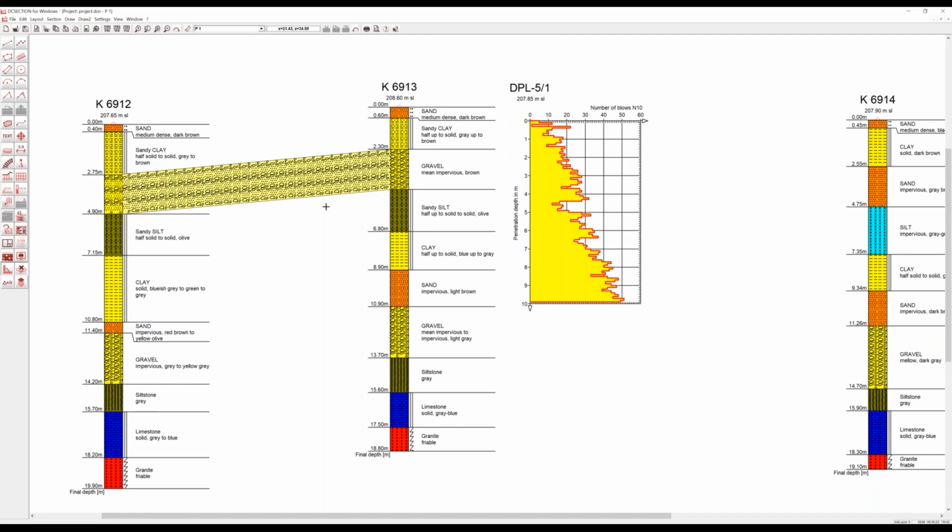In addition to these polygons, we can use splines, so curves for the display of the soil layers. And I can, for example, create a curve here from this point to this point, and there are then 2 control points defining this kind of curve here, and the brown line is the straight connection between these 2 points for selecting the curve later.